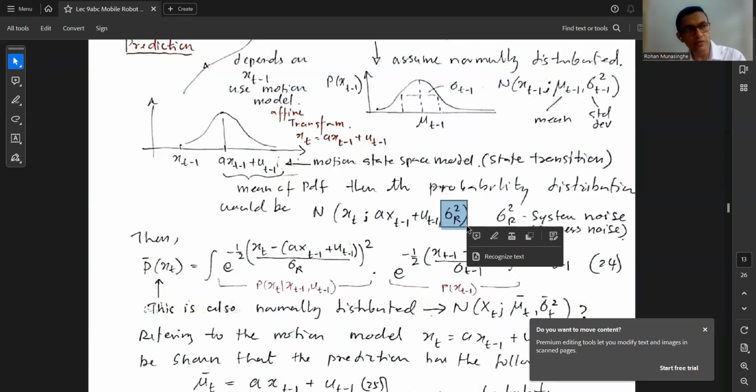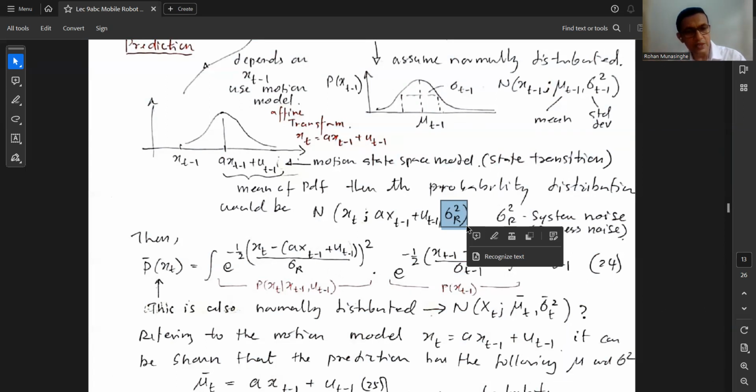So the vehicle model has some sort of process noise that is basically unmodeled dynamics, and it appears as a disturbance. We call it noise, but it's actually not the noise that we know of. It is basically unmodeled dynamics or disturbances and stuff like that that deviate the state, right, a bit differently than what's happening through the state transition equation, this one, okay? So this is a new term coming up over here. So the standard deviation of the vehicle dynamic model is sigma r over here.